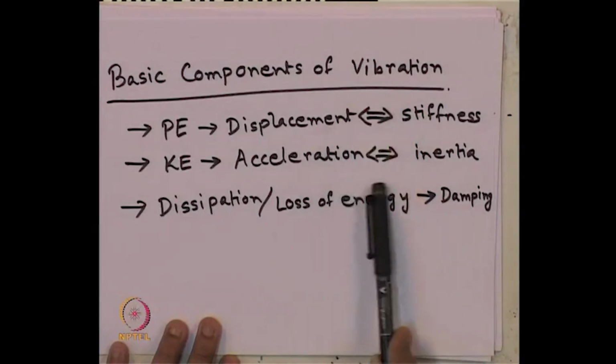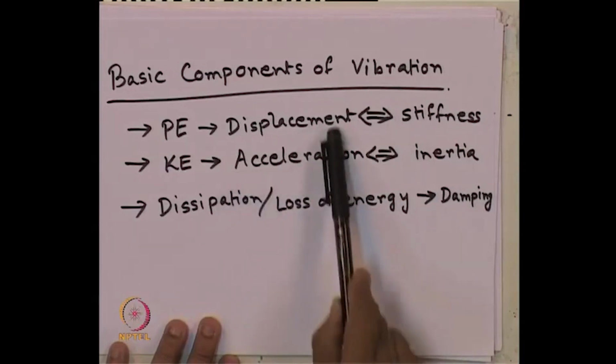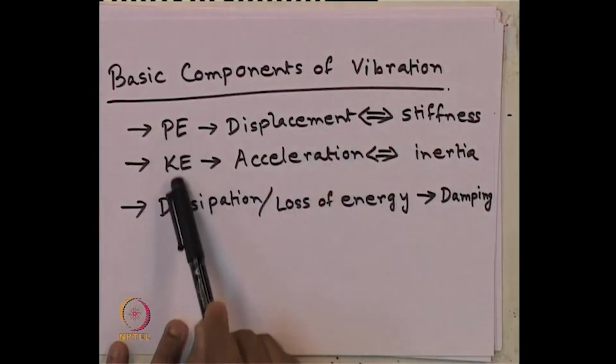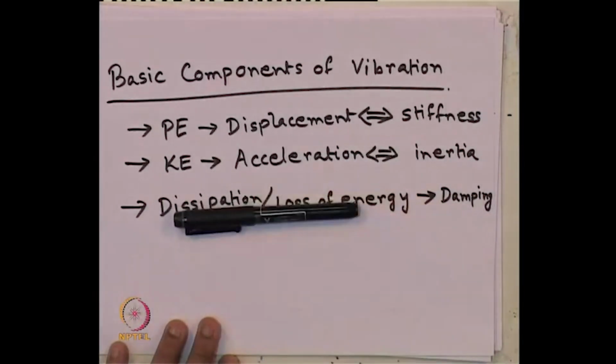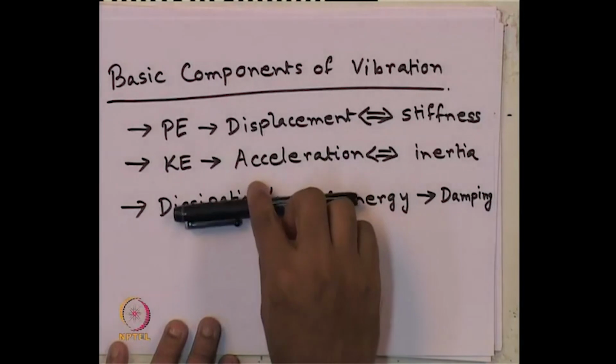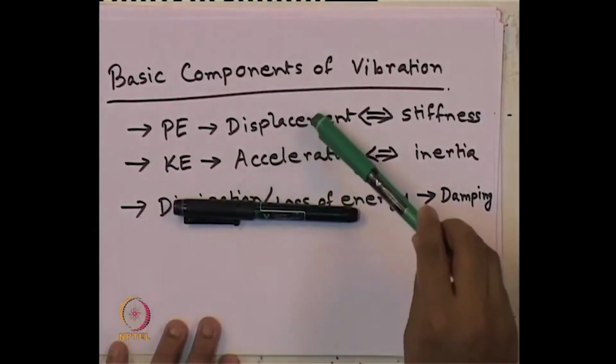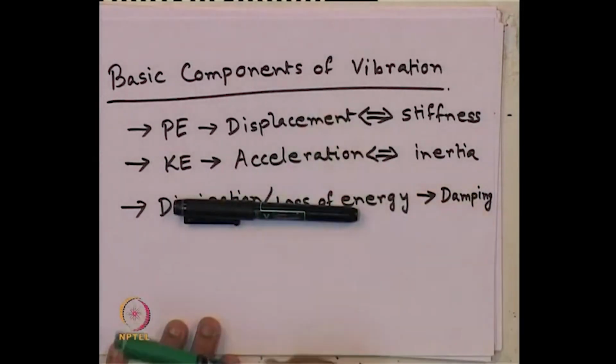The dissipation or loss of energy can be optional, but it must create this exchange of potential energy to kinetic energy in any system, then only the time varying load can be classified as dynamic load. If it is not so, then we cannot say that kind of time varying load is dynamic load.